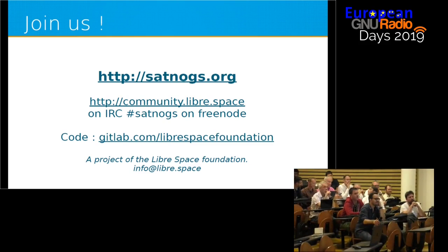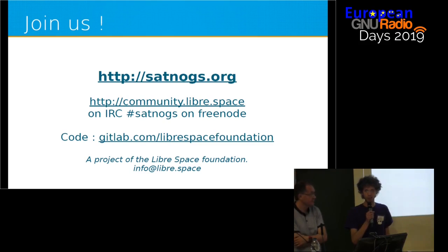Yeah. And there is something special to mention about this. The new geostationary satellite that we have is a very nice playground for SDR, because we have uplink in the 2.4 GHz band and downlink in 10 GHz, and it's the perfect use case, for example, for a PlutoSDR to do the uplink and the downlink. And there are a lot of things to try, but of course, get the license first.